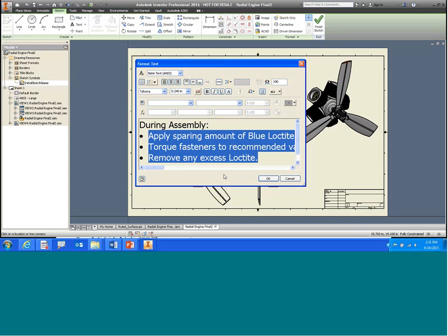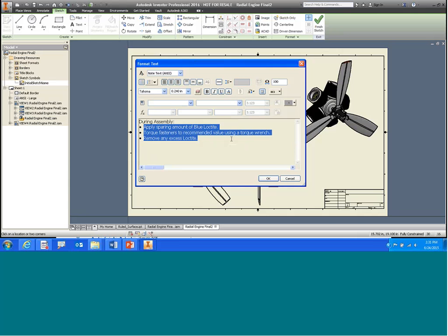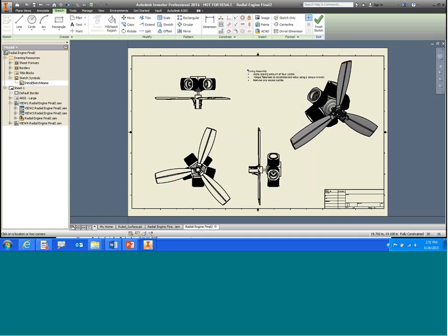In 2015, there used to be a couple buttons down here, and these buttons would enable you to scale the size of the display. Now you actually have to do that with your mouse. So right now I'm holding my Control button and I'm rolling my middle mouse button, so you can see that it's actually reduced the size of my font so I can read it all. It's not changed the actual size of the font for the symbol, but it has made it a little bit more readable. So I'm going to select OK, and you can see that the symbol has now been created on my sheet. I'm going to click Finish Sketch, and I'm going to just add a name for this.